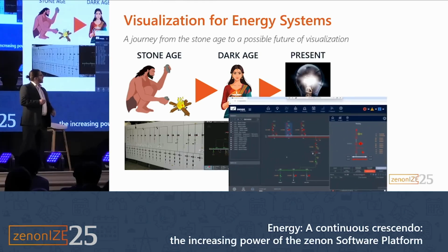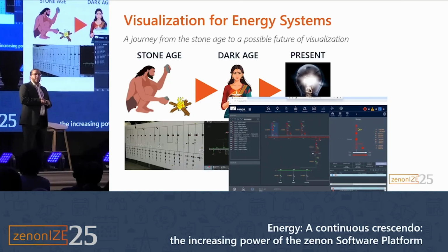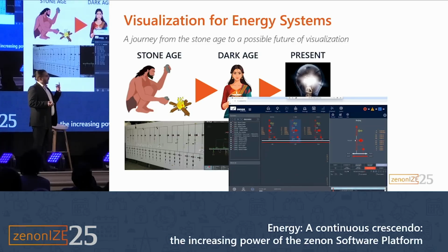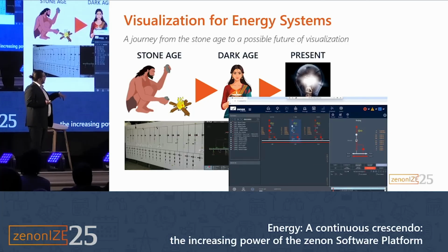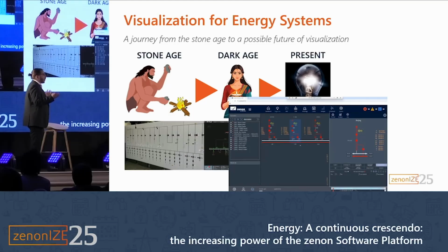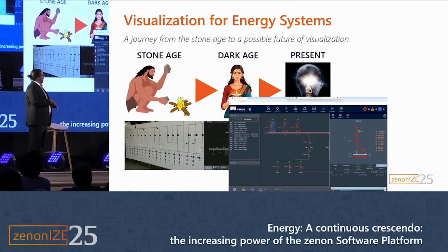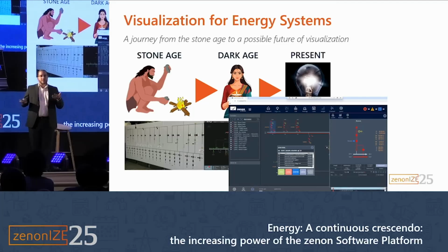So, what can Xenon version 15 offer? On the one hand, you all, or most of you from the energy business, are familiar with command processing. In this case, we offer every command action that does not require the command sequencer to run. You can see in there, at the small control screen, you also have the interlockings, because, of course, you need to see what's going on when you want to switch on or off a switchgear. You also need to be able to unlock things that can be unlocked, in case you know what you're doing.